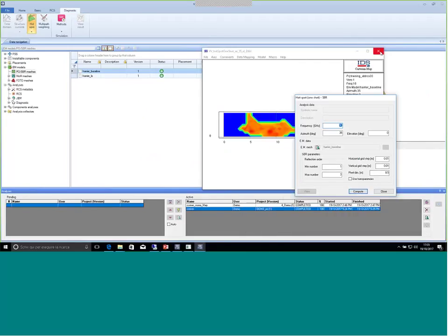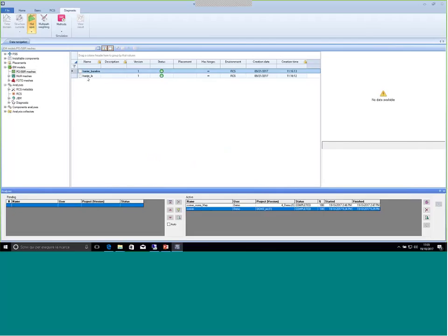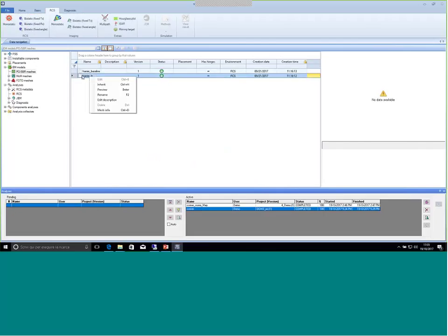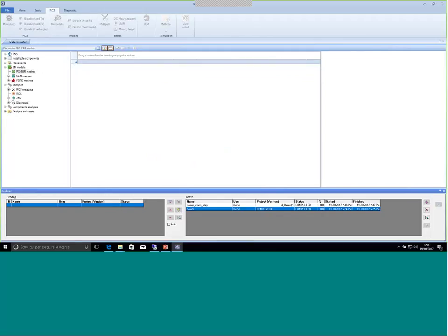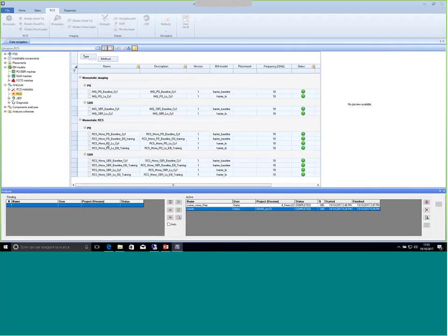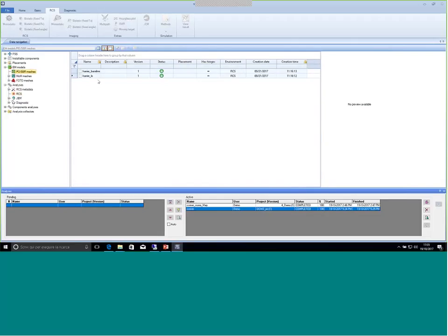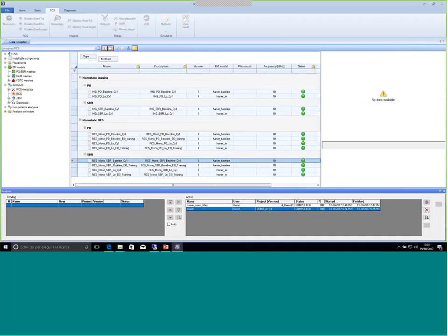And that's exactly what I did here in the low observability model. Let's have a look at the benefits that I got in the overall RCS installing some radar absorbing material on the fin, and actually I have also installed some radar absorbing material inside the cavity of the aircraft.